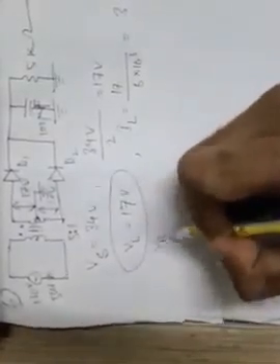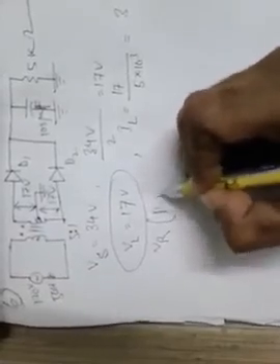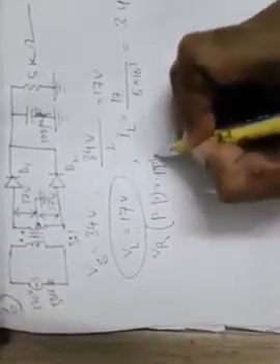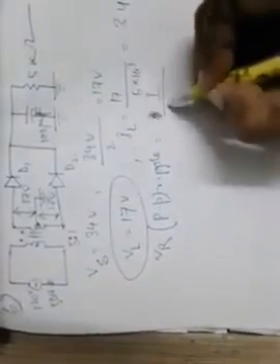Now based on the equation, the peak to peak ripple voltage, like on the previous occasion, is IL divided by f into C. IL is 3.4 milliampere, divided by f, which is 50 into C, 100 into 10 to the power minus 6, 100 microfarad. But here one thing you have to note, you know that for a full wave rectifier the frequency gets doubled.